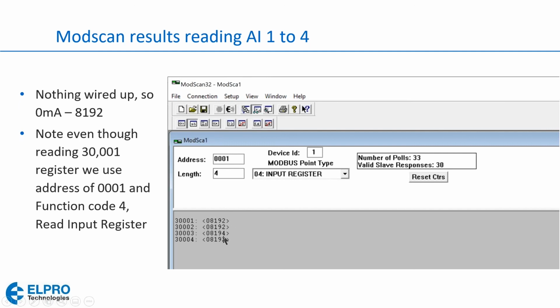We can see one of them is 194, but typically the accuracy is going to be plus or minus, I think I looked it up a long time ago, about plus or minus 10 or 15 byte counts. So usually it'll show you exactly 8192, but if it shows 8194, well within the specifications of accuracy for the radio. You're literally splitting fractions of a hair at this point.